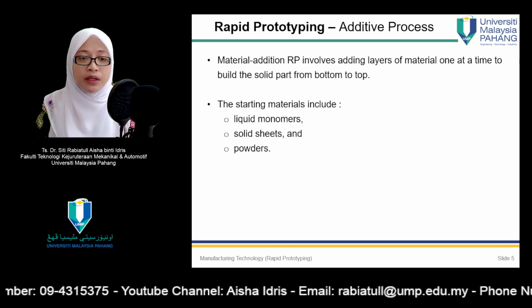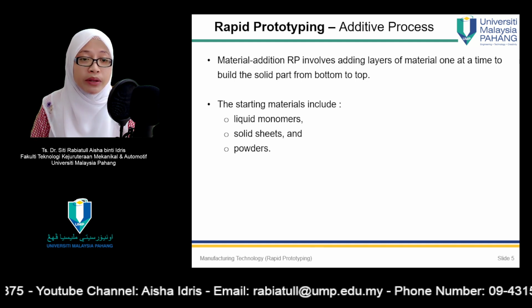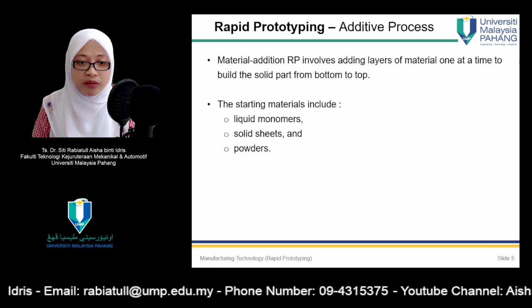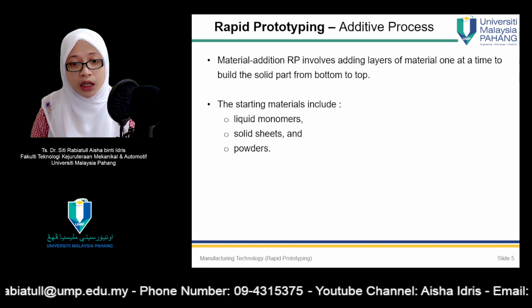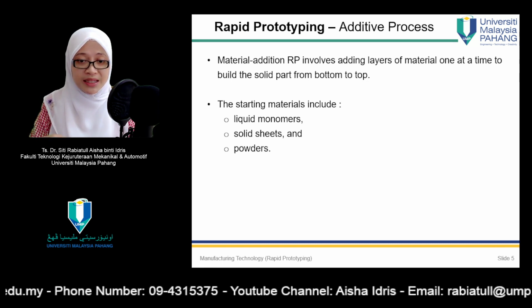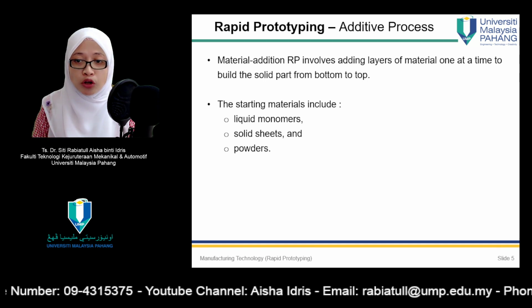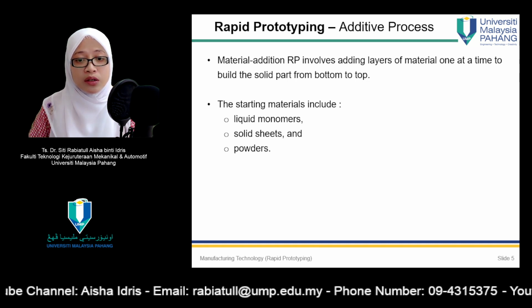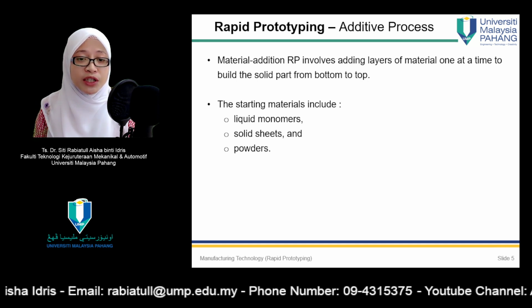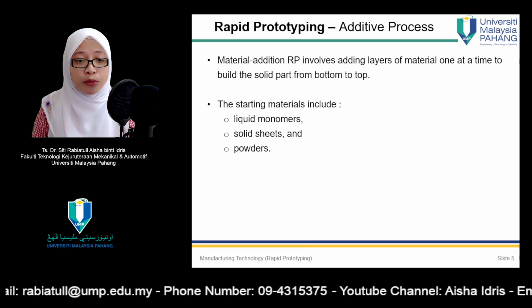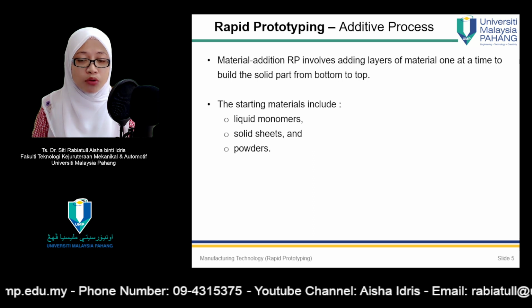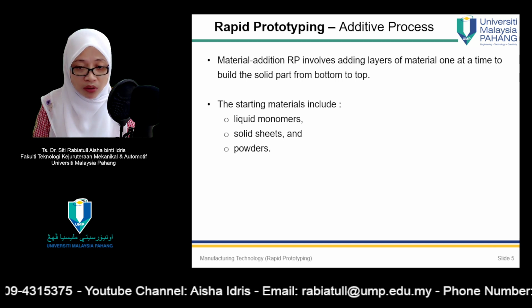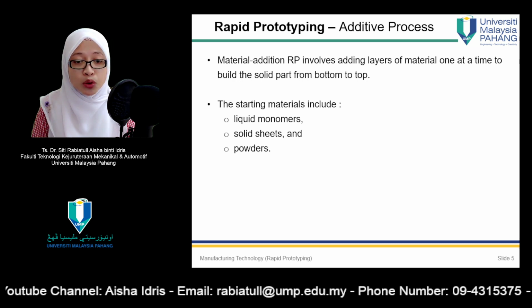Available RP technologies can be divided into two basic categories. Number one is material removal process, and number two is material addition process. The material removal RP alternative involves machining, primarily milling and drilling, using a dedicated computer numerical control (CNC) machine that is available to the design department on short notice. To use the CNC, a part program must be prepared from the CAD model. The starting material is often a solid block of wax, which is very easy to machine, and the part and chips can be melted and re-solidified for reuse when the current prototype is no longer needed. Other starting materials can also be used, such as wood, plastics, or metals. The CNC machines used for rapid prototyping are often small, and the terms desktop milling or desktop machining are sometimes used for this technology.